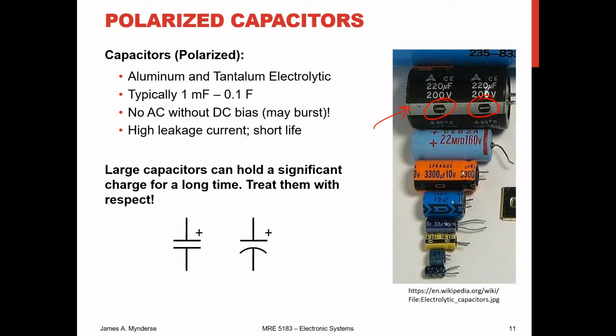Thinking back to grad school, I remember I had a particular circuit board laid out, and I don't remember if I did it or if somebody else did it, but there was a capacitor in there that was reversed. And so when we applied a fairly high voltage, it exploded. Fortunately, it didn't cause too much of a problem. The little filler stuff went everywhere. So always make sure that you don't reverse these. Otherwise, you could see them popping, which would not usually be a good thing.